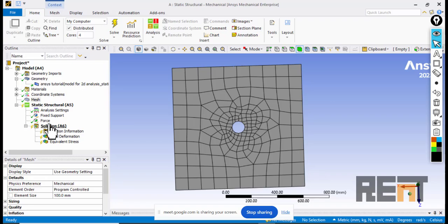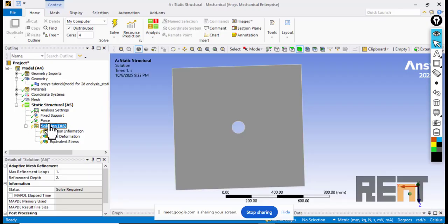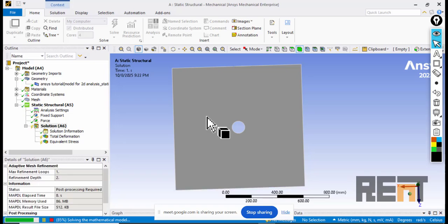After that, probably in our advanced class, we are going to go deep into Ansys finite element analysis in details. They will touch every other aspect of finite element, like the thermal analysis, the explicit dynamic analysis, the modal analysis, the transient analysis. The analysis that we are doing now is static, is steady. The load condition does not change with time. If you are running a transient analysis, you are essentially saying that the load condition will change with time, that the load is not constant.